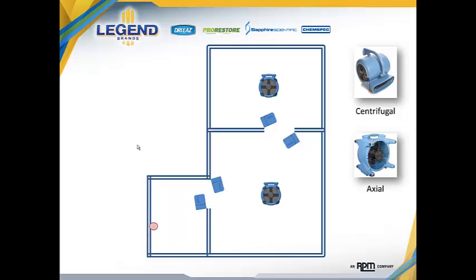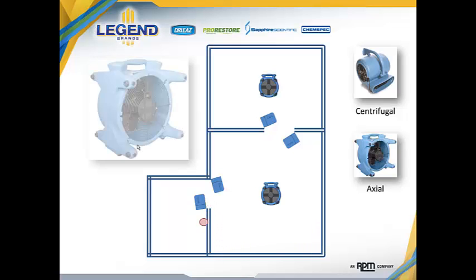Once you've established this, then the other question that often comes up is, how do you install or place dehumidification? And in reality, it doesn't matter. A dehumidification system could go anywhere in this example on this slide, as long as I've got good airflow across the surfaces, good airflow from room to room, it is irrelevant where the dehumidifier goes.